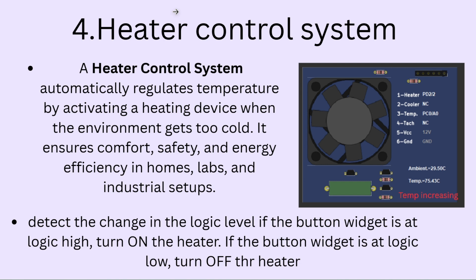Fourth one is a heater control system. It automatically regulates temperature by activating a heating device when the environment gets cold. It ensures comfort and safety, and energy efficiency in homes and labs. Detect the change of the logic level: if the button is at logic high, turn on the heater. If the button is at logic low, turn off the heater. This is a sample of the heater control system.